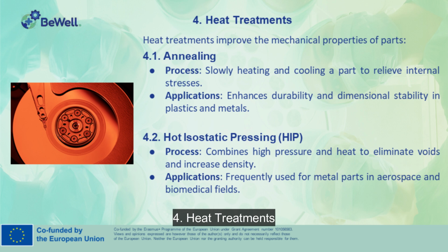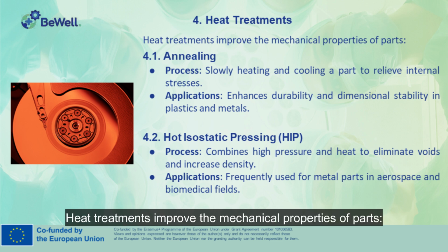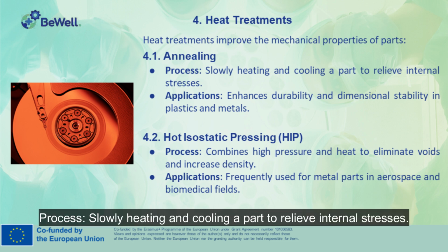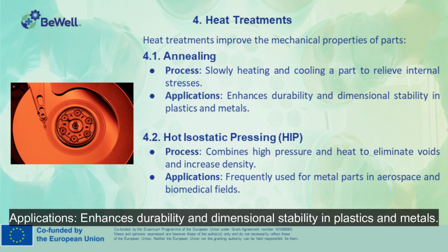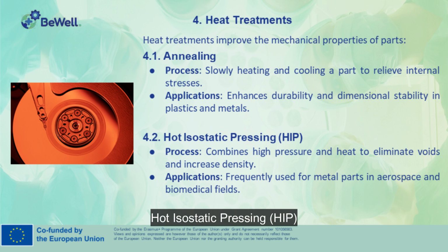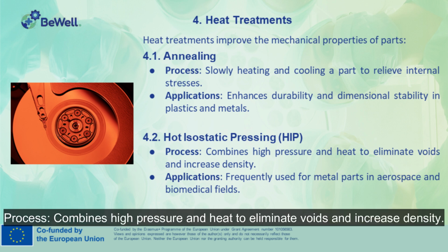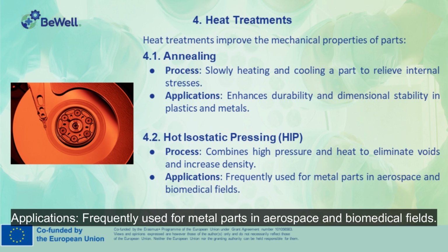4. Heat treatments. Heat treatments improve the mechanical properties of parts. Annealing. Process, slowly heating and cooling a part to relieve internal stresses. Applications, enhances durability and dimensional stability in plastics and metals. Hot isostatic pressing, HIP. Process, combines high pressure and heat to eliminate voids and increase density. Applications, frequently used for metal parts in aerospace and biomedical fields.